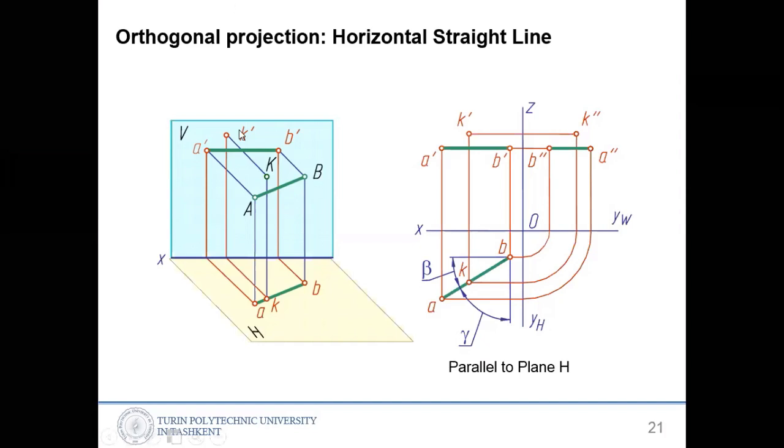If the point K doesn't lie on the real line AB in reality, then in some projections it may still appear to lie on it, because if you see it from the top, it lies there, but in others it does not, because the height of the point K is higher than the position of AB.